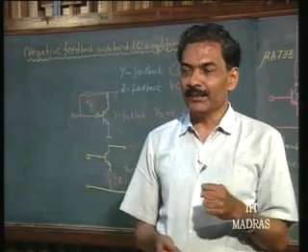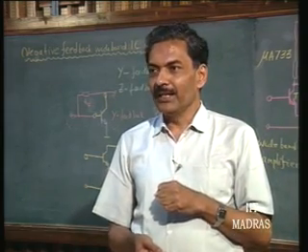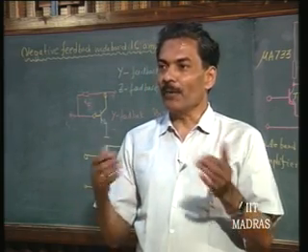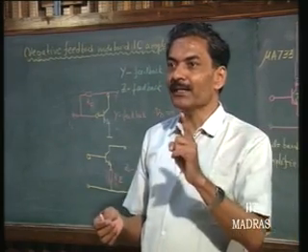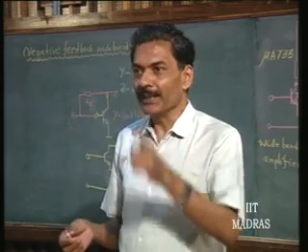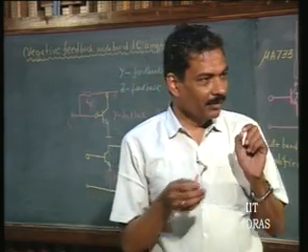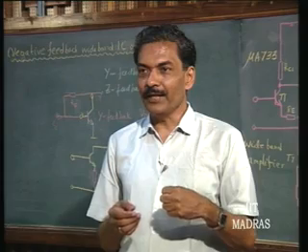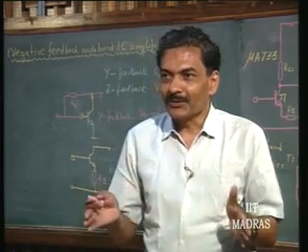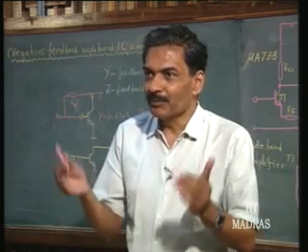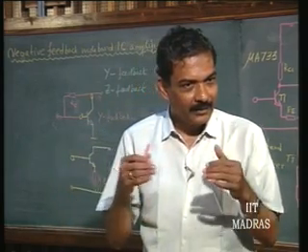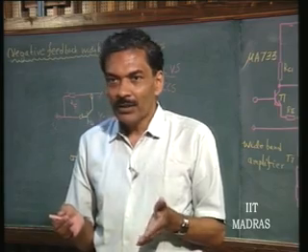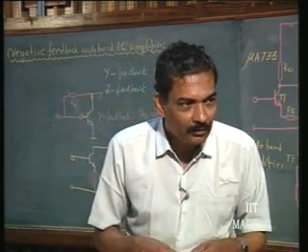What must be emphasized here is, if you take the Y parameters of the transistor and the feedback network, everything put together, and evaluate its bandwidth, you must remember to evaluate the bandwidth of the forward transfer impedance in this case. That will also get modified by the loop gain. That means the bandwidth also is going to improve by a factor of loop gain. Everything improves by a factor of loop gain. In a feedback network, we can always take for granted that improvement is by loop gain. So, the bandwidth also improves by a factor of loop gain.